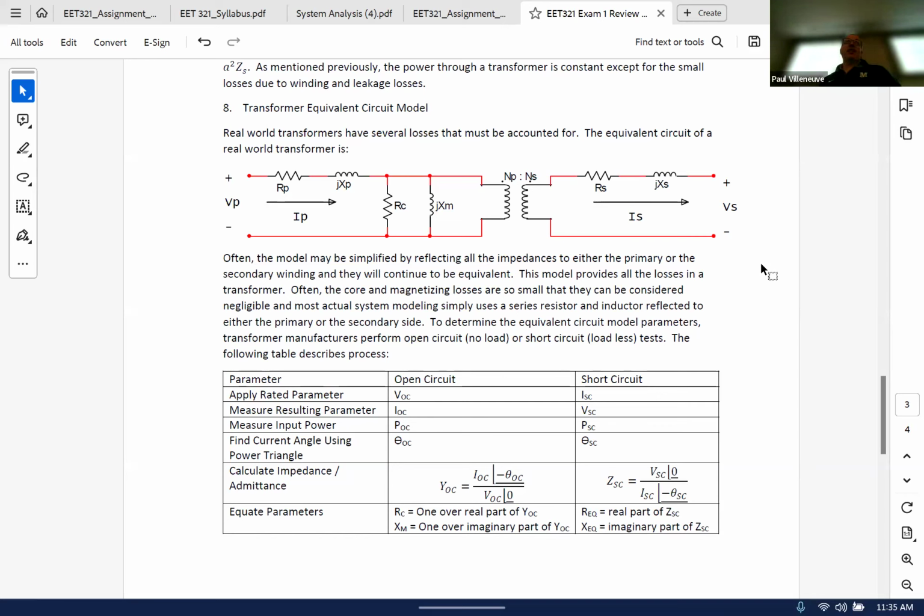So transformers actually can knock down the current without having really a major impact on the losses of a system. So that impedance that we have in a transformer is a good thing. That's sometimes why, if you saw in the problems, we talked about the short circuit impedance, one of the examples we had in class. The transformer data sheet doesn't really show it in there. There is a %Z term that, if you really dig around, makes sense to you. But the concept is that's what the effective impedance is of the transformer, and it brings the current down.